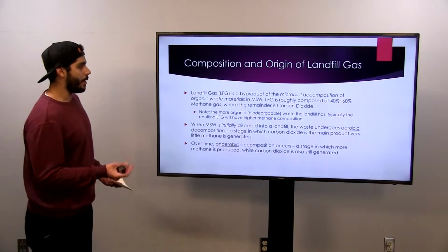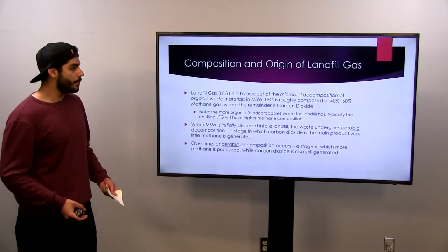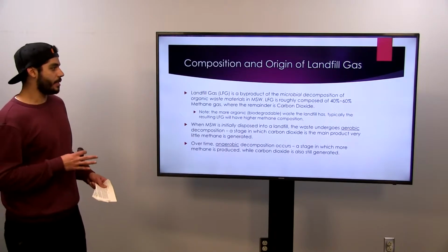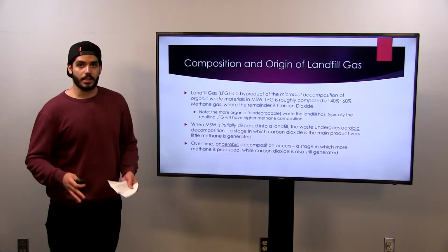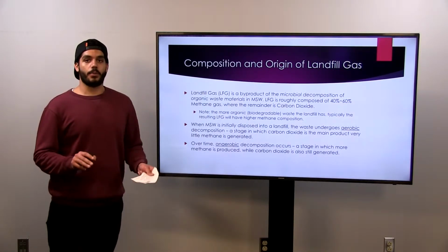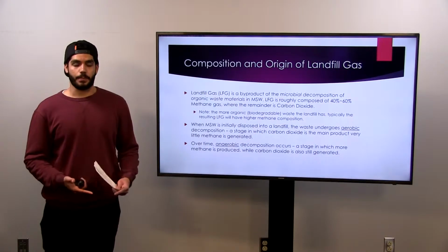So landfill gas is a byproduct of the microbial decomposition of organic waste materials in MSW. Landfill gas is roughly composed of 40 to 60% methane gas, where the remainder is carbon dioxide, which is another byproduct of this microbial decomposition. Now, the microbial decomposition is broken down into two steps, the aerobic and the anaerobic decomposition.